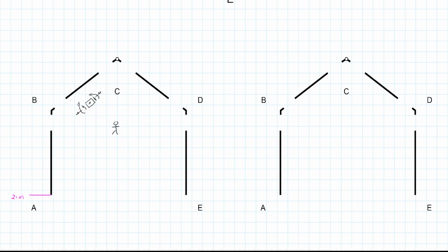And so we can draw in our shear force diagram. Remember, it is linear, and that gets us to negative 3.91. It's linear because of the uniformly distributed load of 5 kilonewton per meter acting on it. And then I'm just going to very quickly use similar triangles to compare the total change, 25, and figure out what this distance is here. And that distance is equal to 0.78 meters.